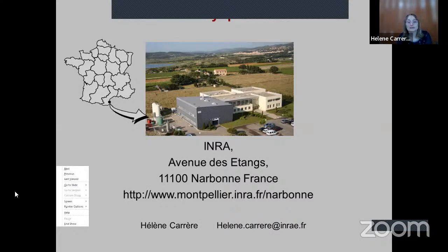Okay. So we need a pre-treatment for that. Pre-treatment, whether it's becoming like a block or drying it first, something like that. Yeah. And the second problem is that thanks to anaerobic digestion, we will never go down to a very low value of COD at your outlet. So you still need some finishing with an aerobic process. Okay. So there's still an aerobic process.